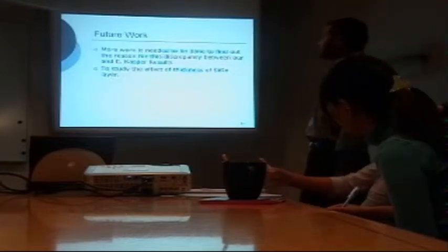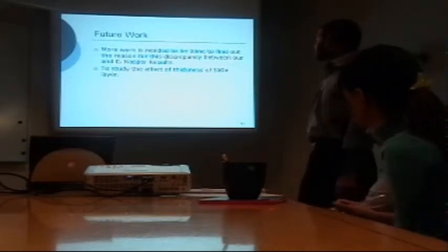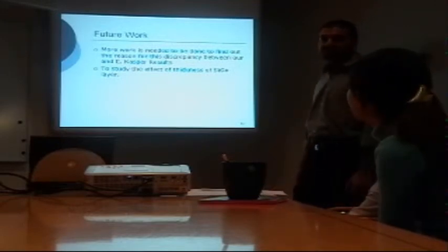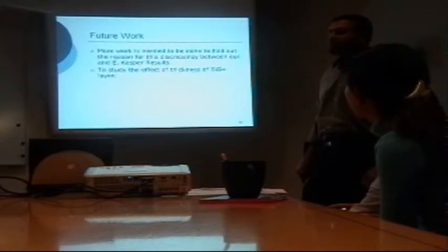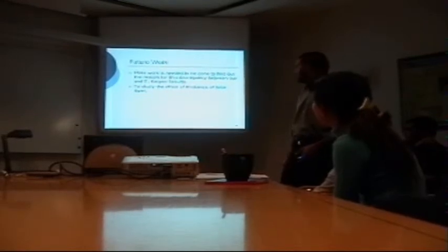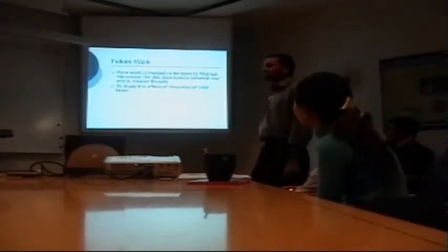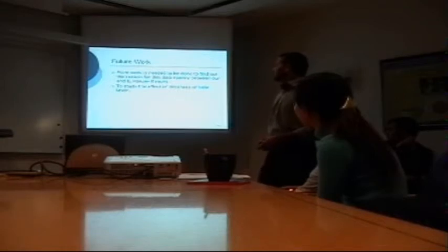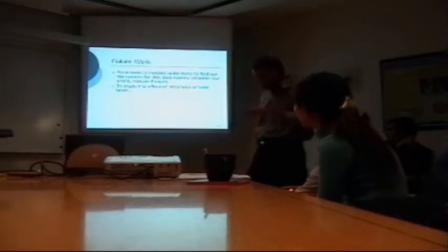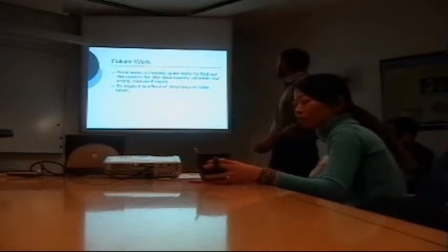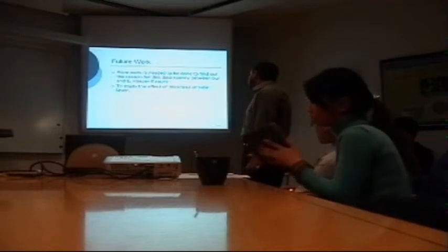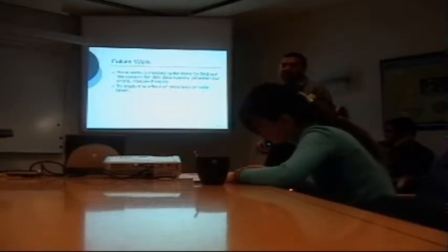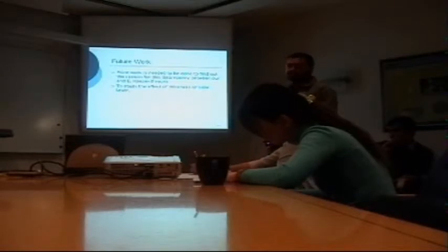So, some suggestions for the future work. First, more work is needed to find out the discrepancy between our results and E. Casper's results in terms of relaxation and surface roughness with respect to the change in temperature. During the present work, we studied the temperature effect on the silicon germanium layers in terms of relaxation, surface roughness and high relaxation. But I suggest that we should study the thickness effect of the silicon germanium layer, and also study the variation in surface roughness and relaxation.